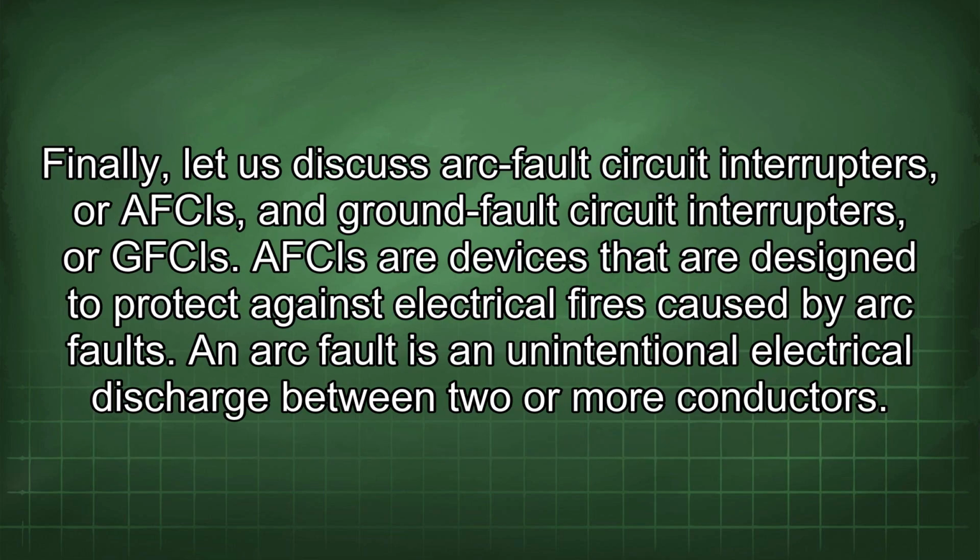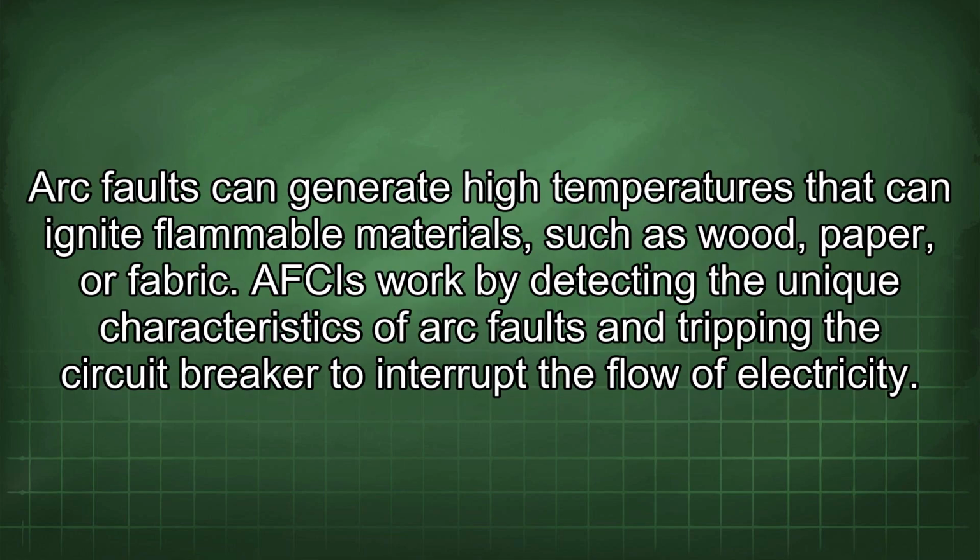Finally, let us discuss arc fault circuit interrupters, or AFCIs, and ground fault circuit interrupters, or GFCIs. AFCIs are devices that are designed to protect against electrical fires caused by arc faults. An arc fault is an unintentional electrical discharge between two or more conductors. Arc faults can generate high temperatures that can ignite flammable materials such as wood, paper, or fabric.